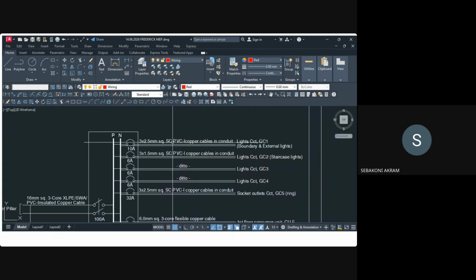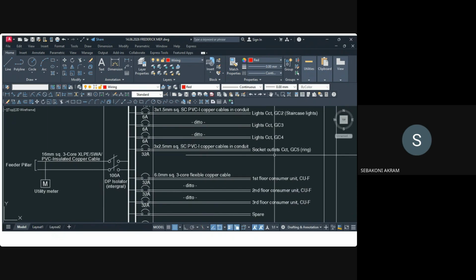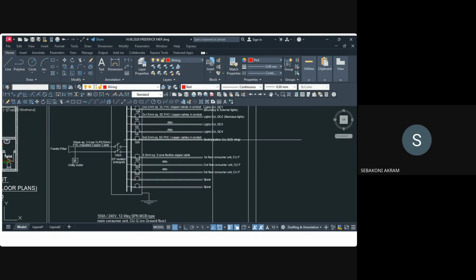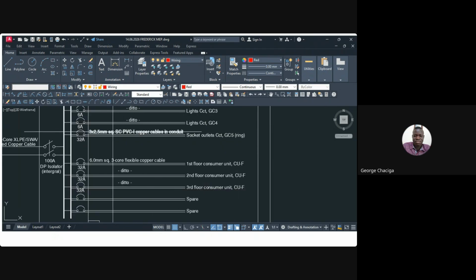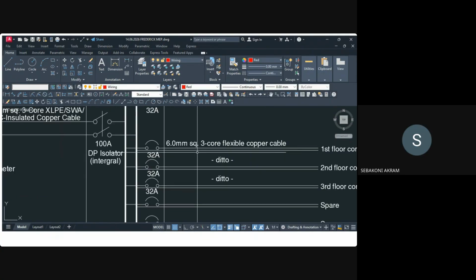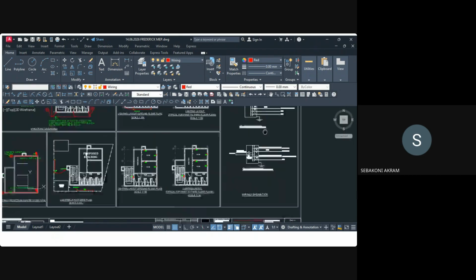There are some elementary things that you will just be seeing. You know that, based on these lights, I might need lighting cable of 1.5, which I know you know. Socket outlets, usually they are 2.5. But the number of sockets on that cable also matters, and the expected load that is going to be connected.